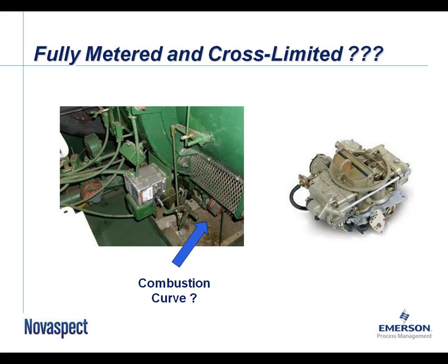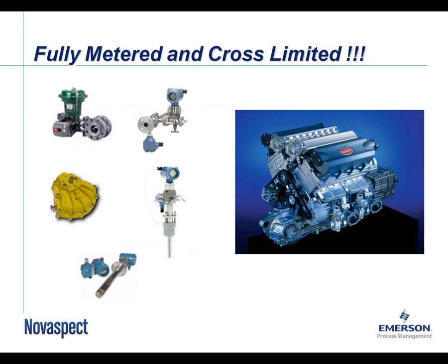I'm not saying it didn't work, but if the air filter got plugged or anything, big temperature changes, it would smoke and not run very well. And again, that comes back to it's just relying upon damper positions and shafting to keep everything in the right firing rate, as opposed to new engines today that use fuel injection, where they measure both the fuel and the air, set those set points so that they're always in the correct ratio, and then control the air and the fuel flows. And that's what we see here with some of these pictures.